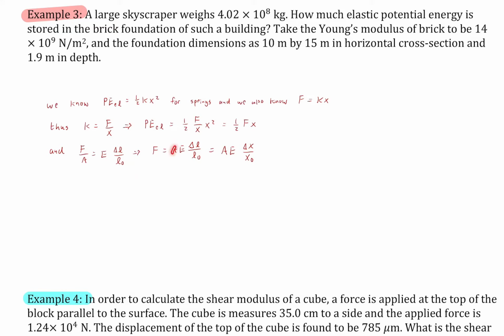So we've got a cross-sectional area, the elastic modulus, and the change in length over the original length. And then I'll write this in terms of x. The reason I'm writing it in terms of x is because I already have my original formula in terms of x. That x must be the same as the length, or at least be related to the length. That's the only dimension we care about, the same dimension that we called the depth up above. So I'm just clearing up the variables here by using x instead of L.